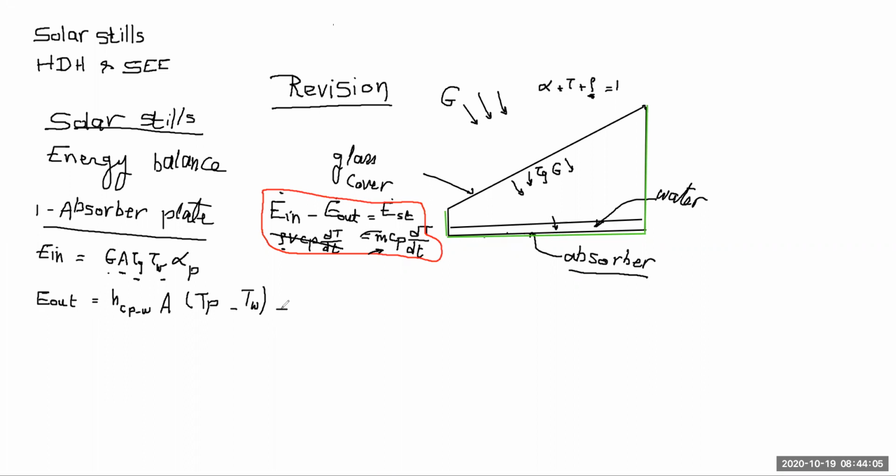What else? We have insulation, which means that although there's insulation, what does it do? It reduces the heat transfer rate, but it does not eliminate it. So we have to have some sort of Q losses. Say that the insulation is made of fiberglass. Fiberglass does not have zero thermal conductivity.